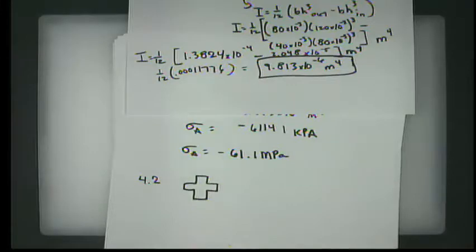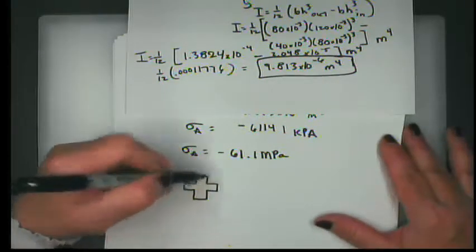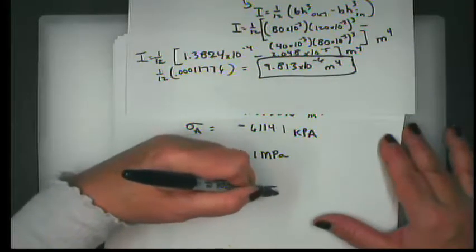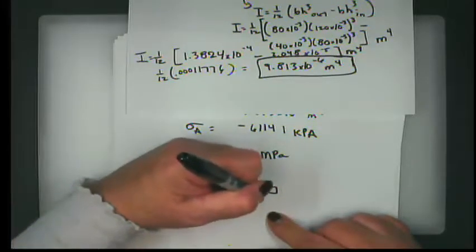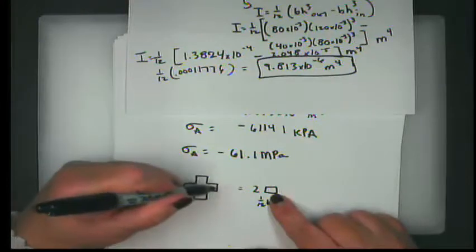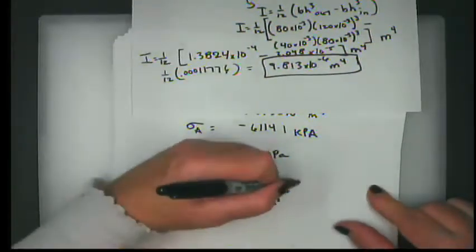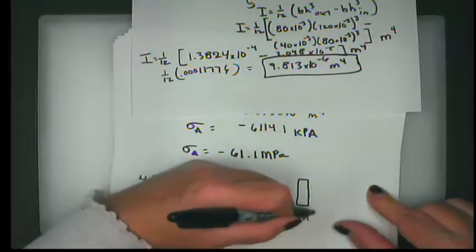all right, there's a couple of different ways to do it. But what I would do is break it down into 2 times the little arm, okay? And that would be 2 times 1/12 base height to the third of the little arm, this and this. And add to that the larger rectangle, 1/12 times the base times the height to the third of that.